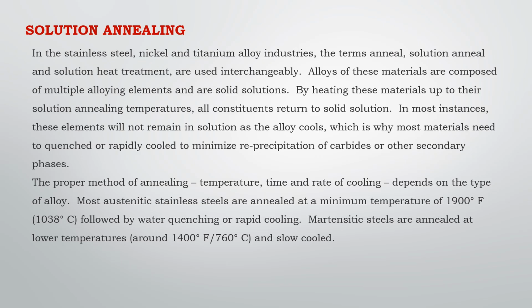In the stainless steel, nickel, and titanium alloy industries, the terms anneal, solution anneal and solution heat treatment are used interchangeably. Alloys of these materials are composed of multiple alloying elements and are solid solutions. By heating these materials up to their solution annealing temperatures, all constituents return to solid solution.